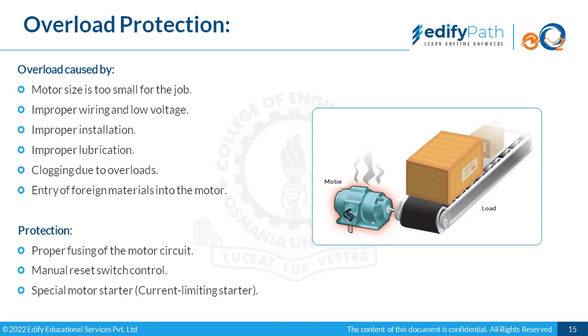We keep on checking the amperage drawn by the motor. If it is under proper levels, then only we should continue with the process. At times, because of problems in the bearings or other internal issues, the motor starts taking more current than the rated one. At that time we have to overhaul the motor, within a particular time, so that the burning of the windings or other major fault doesn't occur or affect the process and the motor.